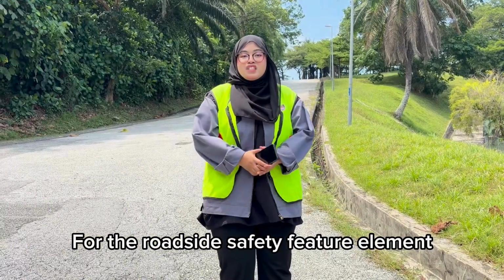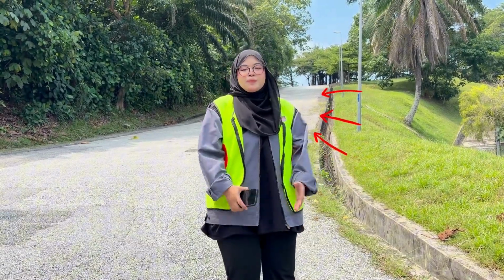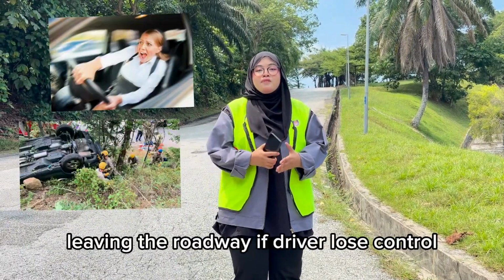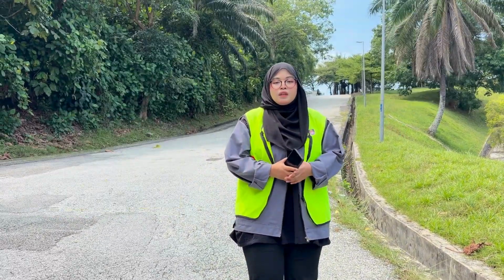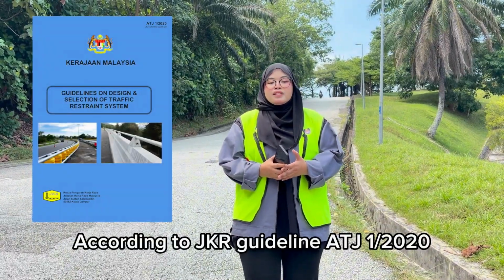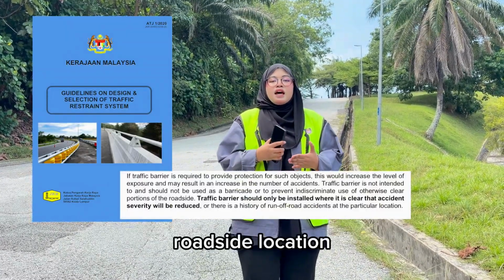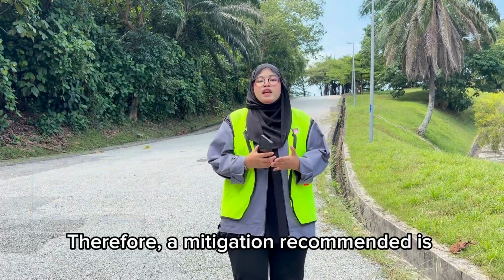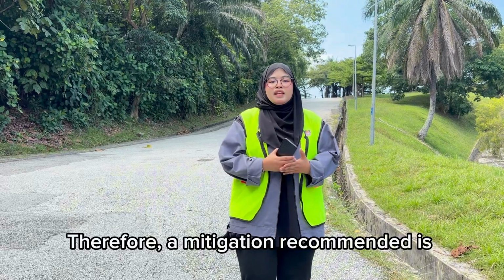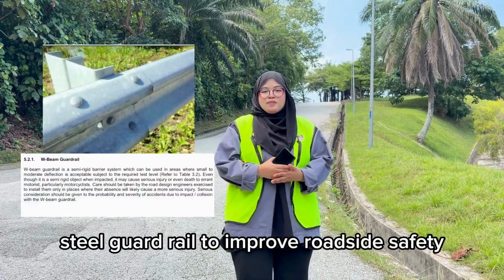For the roadside safety feature element, we observe that no guardrail is provided along the steep roadside section. This may increase the risk of vehicles leaving the roadway if the driver loses control, especially during wet weather. According to JKR Guideline ATJ 1/2020, traffic barriers should be provided at hazardous roadside locations where there is a risk of run-off-road crashes. Therefore, the recommended mitigation is installing a double beam steel guardrail to improve roadside safety.